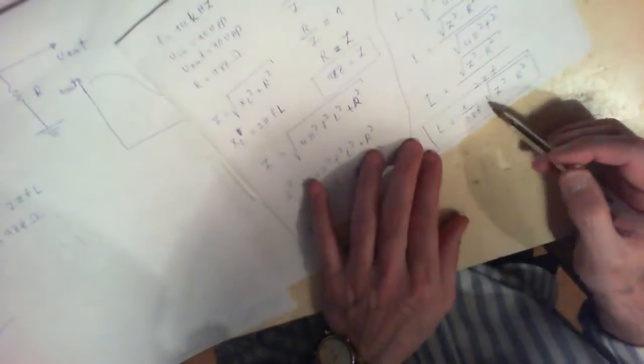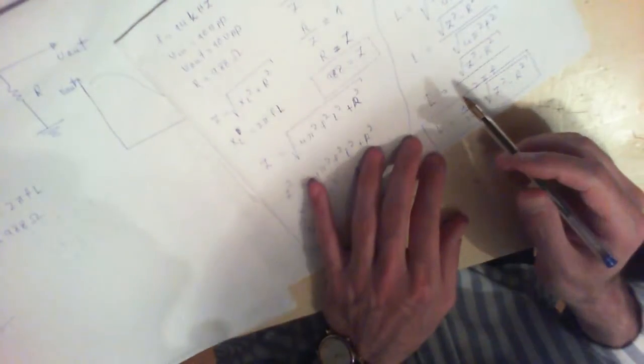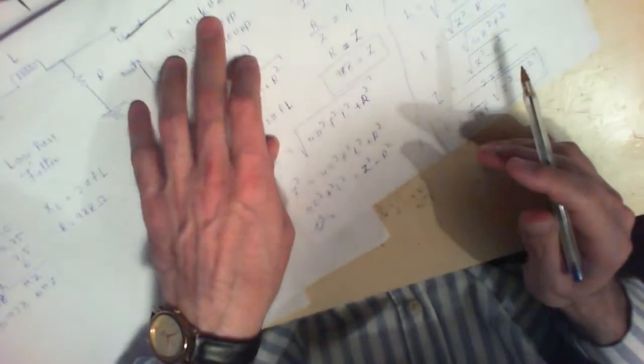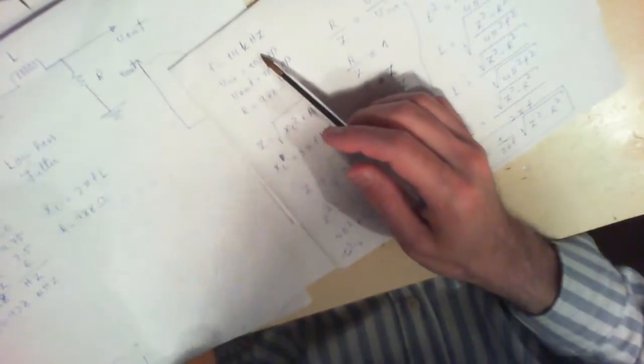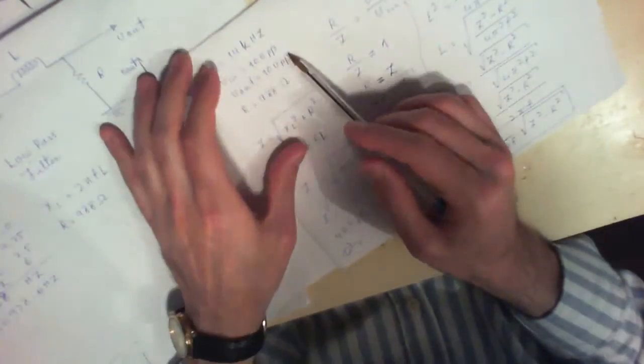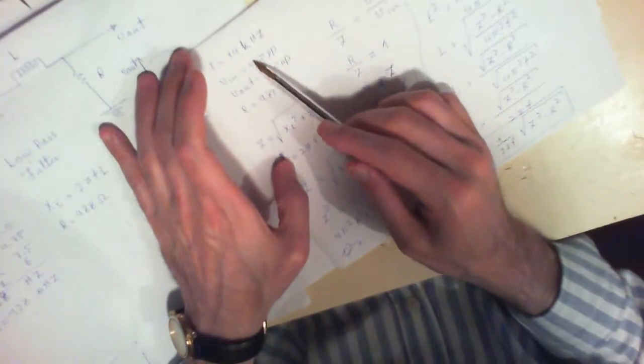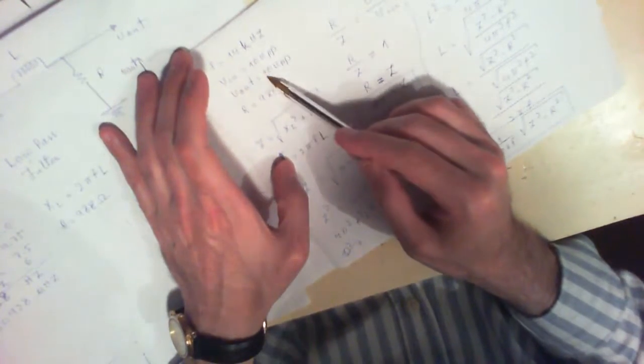The test circuit that you could make is a low pass filter, keeping the frequency relatively low, something around the same frequency that we had here, about 14 kilohertz or so, and then find some spots on your oscilloscope screen where the input and output voltages are exactly the same.